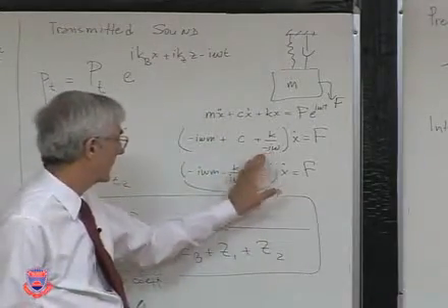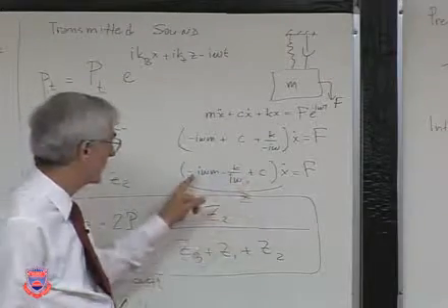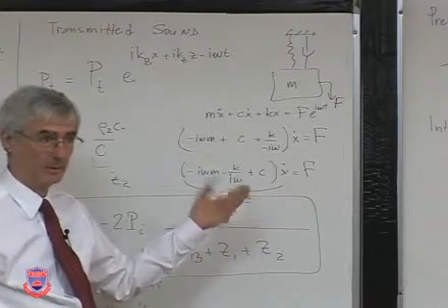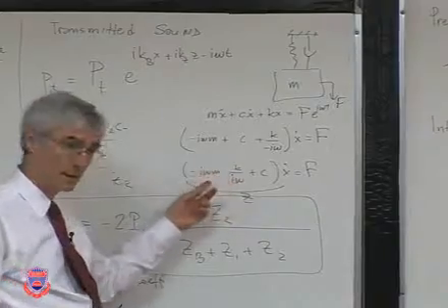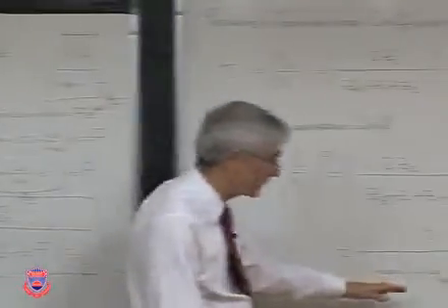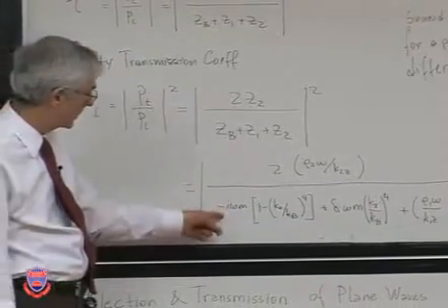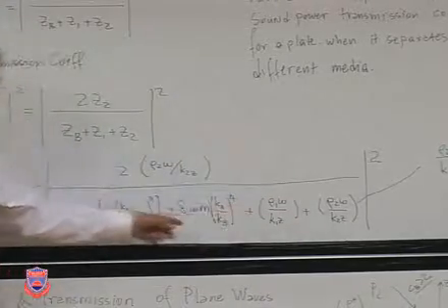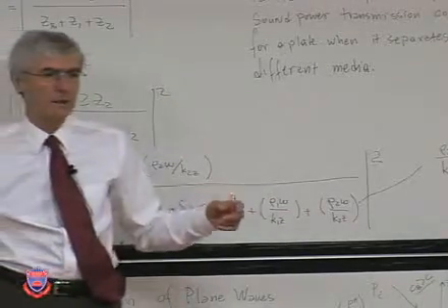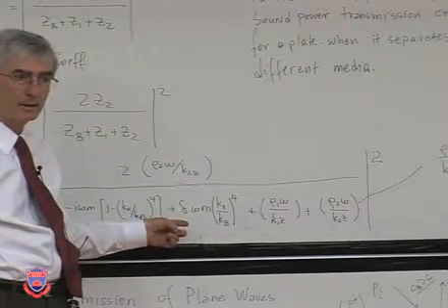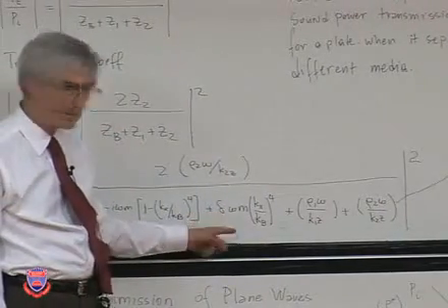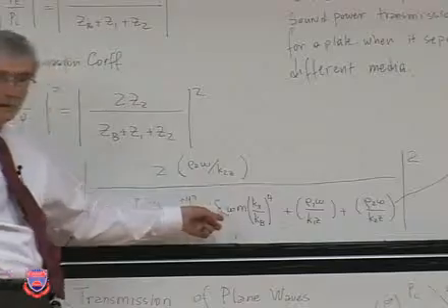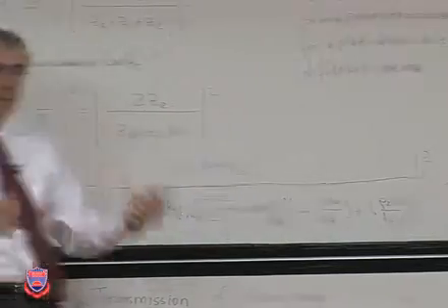Okay? If you don't have that, you only have the reactive part. And what does the reactive part correspond to? If it's zero, we call it the resonant condition. Okay? Stiffness and inertia. So when you look at equations like this, when there's an impedance, you look at the imaginary part, the reactive part, and you look at the real part. Real part, we said energy is dissipated. How's the energy dissipated here? Exactly. Okay? Delta here describes the material damping of the plate.